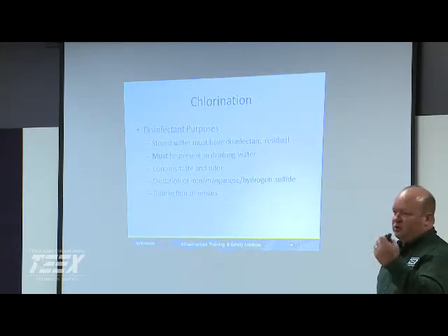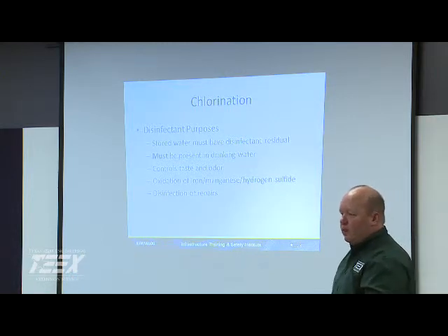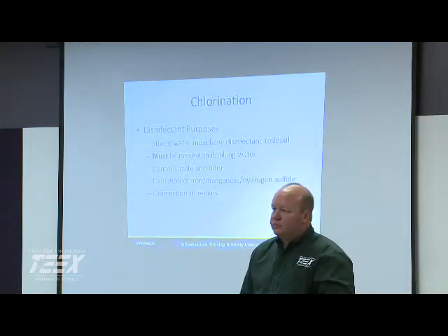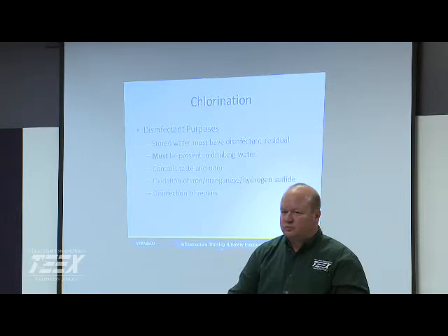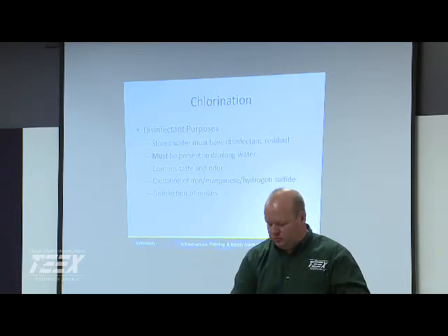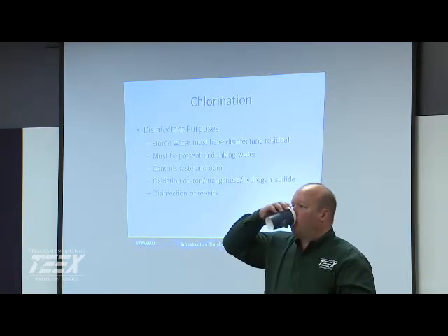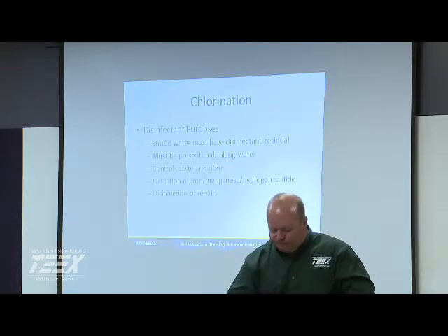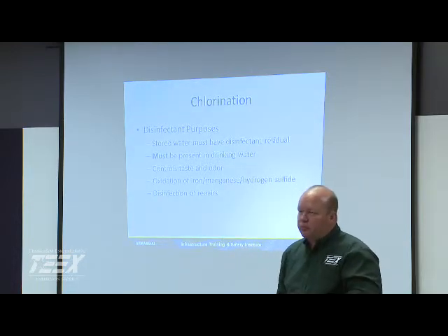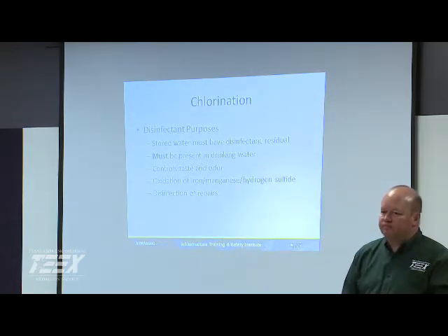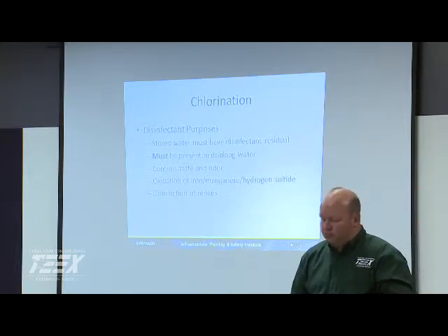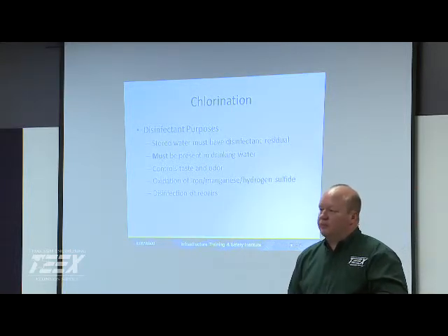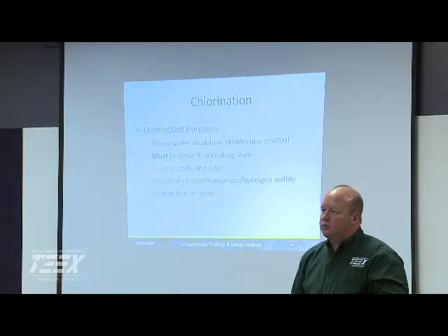Right, yeah, if you do it hot. Yeah, that's part of our rule requirements, that if you can maintain positive system pressure until you get down to the main and clean the area before you actually cut off the system pressure, then we've allowed that you can swab the interior of the replacement main and the cut ends. Right. And go ahead and flush it and pull back two samples.